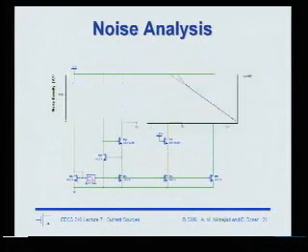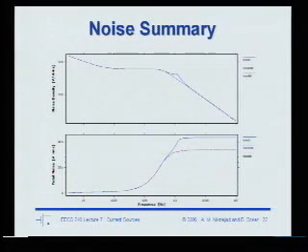Okay. So here it is. This is the noise result. So this is the noise density, and you can see that they're all right on top of each other at low frequencies. You have your flicker noise, then you have your thermal noise, and then at high frequency they start dropping off. Except you see the boosted amplifier has a little bit more noise. Okay. Now I say a little bit because I'm looking at this curve. Does that matter?